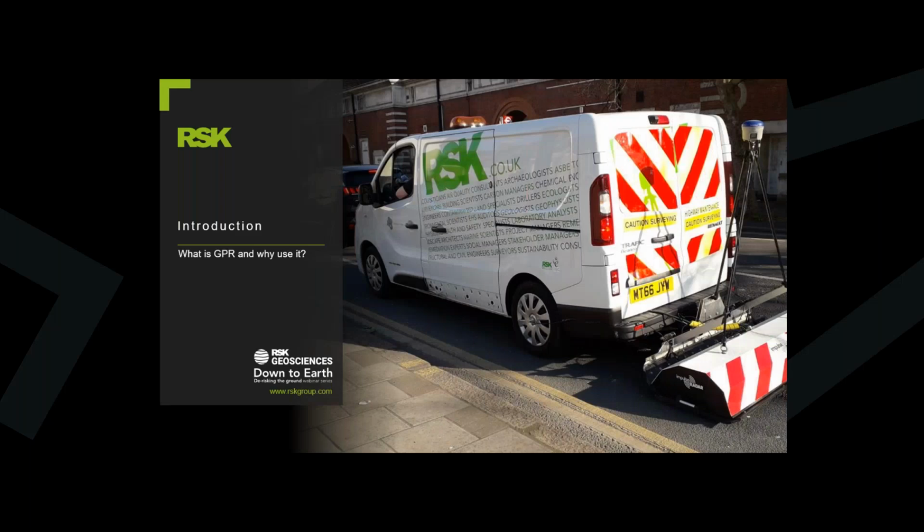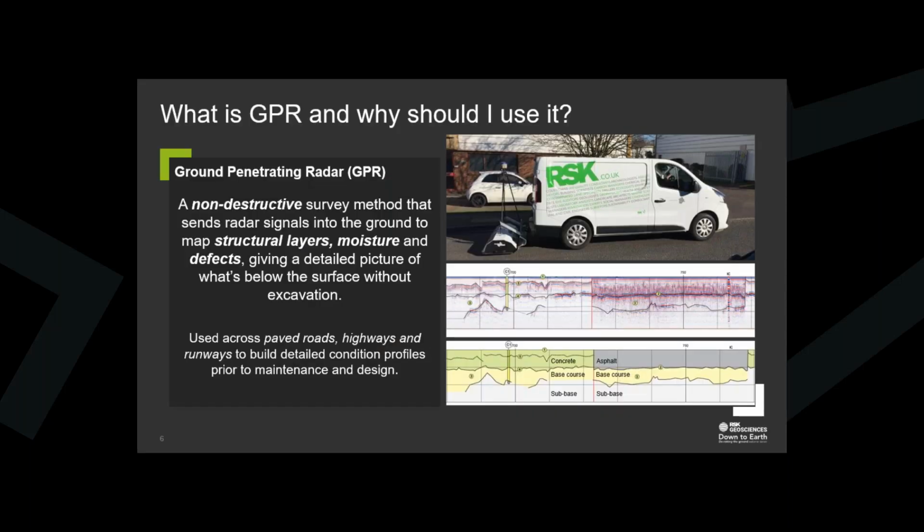We will begin with a look at what GPR is, how it works, and why we use it. The image there is just one of our vehicles with a bit of trim missing, unfortunately, with one of our towed GPR array systems. GPR is the most commonly used geophysical technique for highways assessment, as huge amounts of data can be collected rapidly with minimal disruption to traffic flows.